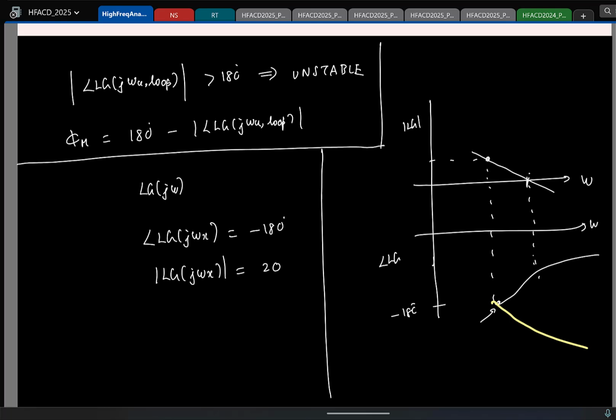Right? And if the phase has to continuously reduce like this, can you tell me if the system can have left of plane zeros? If the phase has to continuously reduce, do you think the system can have left of plane zeros? It cannot have. So if I give you an additional condition that, let us say it is an all pole system, then this is the third information given to you, then you can conclude that this is unstable. Otherwise you cannot make any comments.